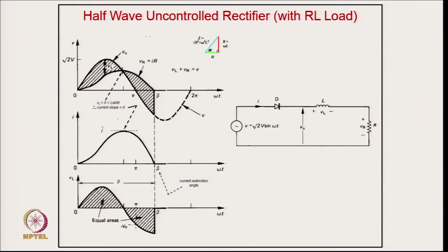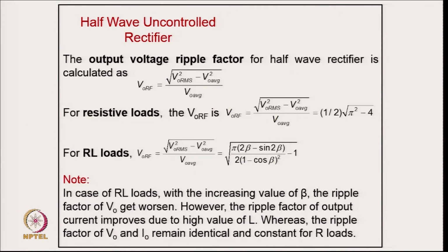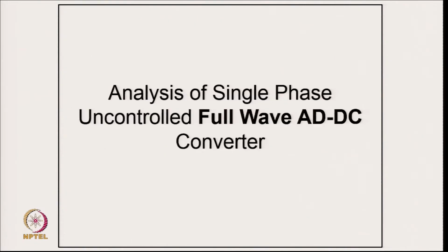So, you can see how the current will be drawn from the supply in this shape. Ideally, we should take a sine wave, but you are drawing the DC component also, not only the AC component. That is the kind of supply current you typically draw from a diode, and this is the voltage across the capacitor, across the load. Then you can calculate the output average voltage and RMS voltage. Such a load will certainly cause a reasonable power quality problem.